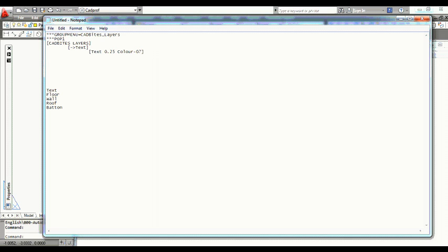This is the first bit of code that we're going to use to actually generate the script. First of all, whenever you're in AutoCAD, you want to ensure that before you start this command you hit escape twice, and the DIESEL script for that is ^C^C, and that'll kick you out of any commands. Now, if you remember from the introduction, the next bit was layer, and we want to suppress the dialog box, so we hit -LA.